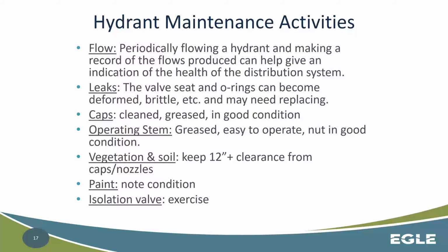Hydrant maintenance activities. Flowing hydrants periodically is an extremely important part of maintenance in a distribution system. Making sure that hydrants are operable is very important. Identifying leaks from the valve seat and the O-rings can be important. We want to make sure, because over time they can get deformed, brittled, and other things can happen like we saw here. So making sure that you understand when the hydrant has a leak is very important, especially when we get into